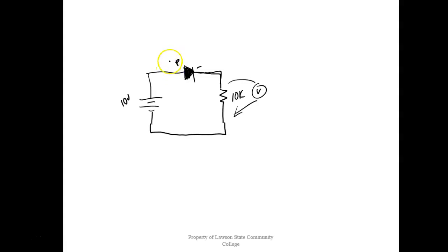And then I put a voltmeter across the diode. I'll take a guess. We're just measuring volts. No, we're going to get 0 volts right here, and we're going to get 10 volts right there. The diode is set up to block. But that's a good guess.